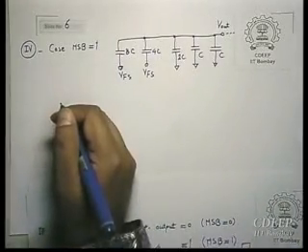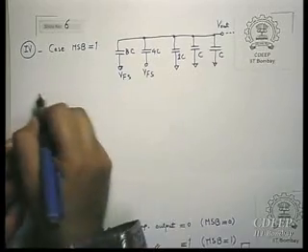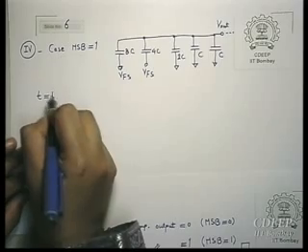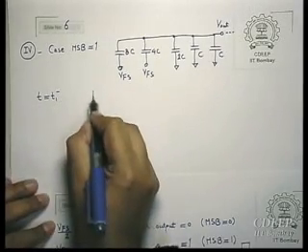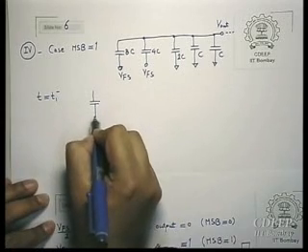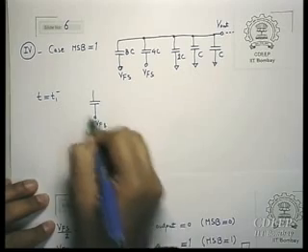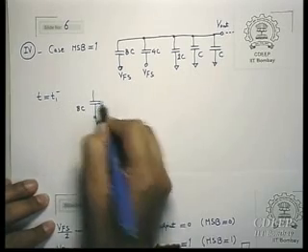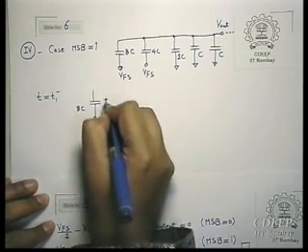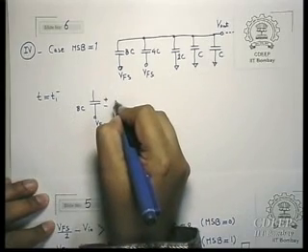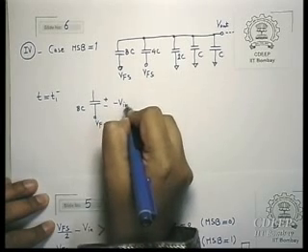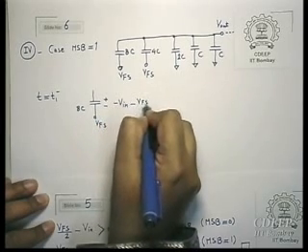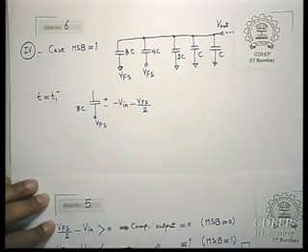So before connection, first let's make it, say for example, T1 minus. At T1 minus, what has been the situation? This capacitor, this was V full scale, this is 8C, and the voltage here, if you look at the voltage in this way, this is minus V in, minus V full scale by 2, right? This was the condition.